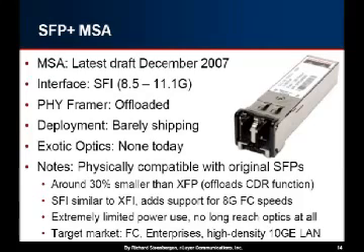Also, this is a little bit smaller than XFP. It's about 30% smaller, which is not a huge amount. XFP was already pretty small. But basically, they offload the CDR functionality. I'll talk more about that in a bit. But expect the target market to be fiber channel enterprises and very high density 10 gig.